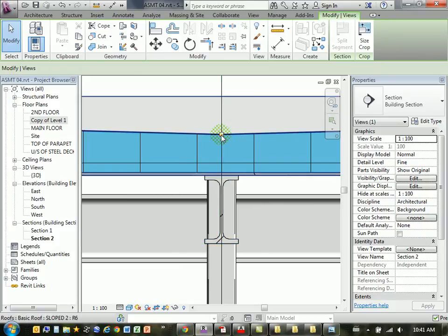Now the last thing we want to do is actually drag this point off to one side or the other, because what this represents is where we would actually have a pipe. So we'd have a little trap with a filter on it, and then that would lead into a pipe, and that pipe would drop down through the building and actually drain the water from the roof. So we can't have it colliding with the structure.